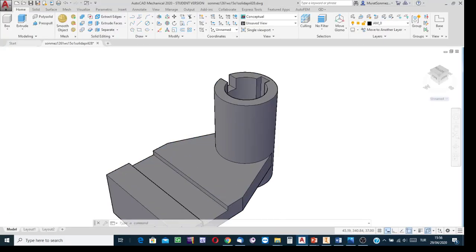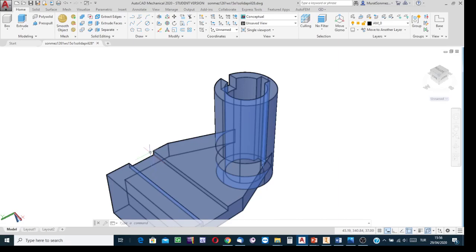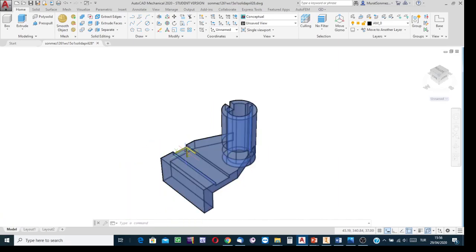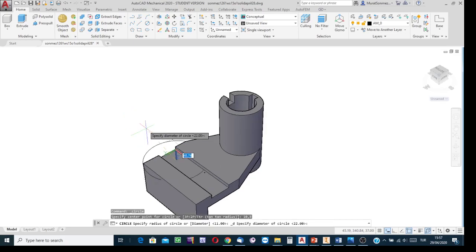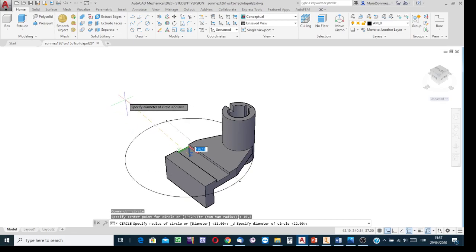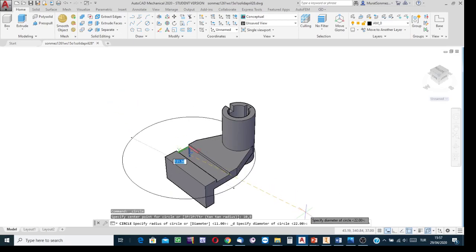Since the origin is over here, at this corner, according to it write the xy values for the circle to have. I start the circle creation process. The abscissa value is positive 10. Click on the comma key. The ordinate value is positive 8. Press enter. Here is the center of the circle. The diameter of the circle, I forgot the number.